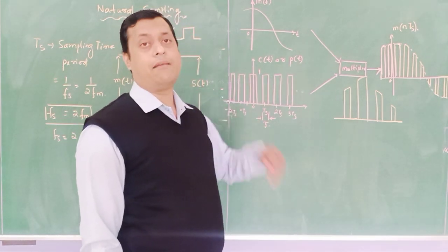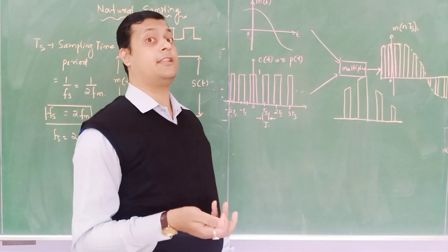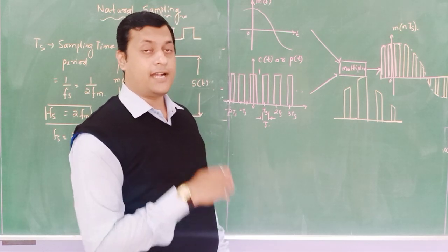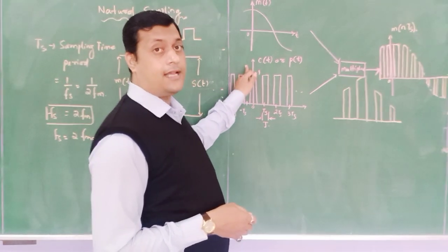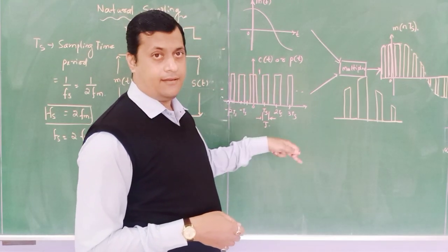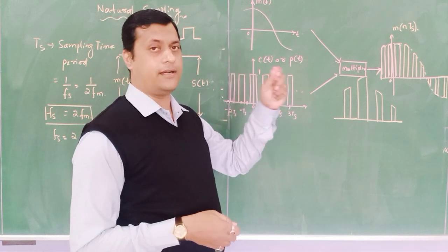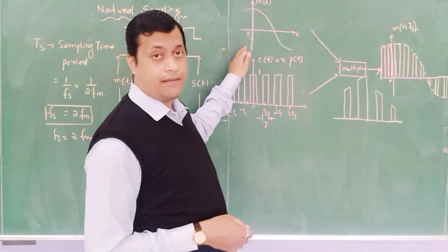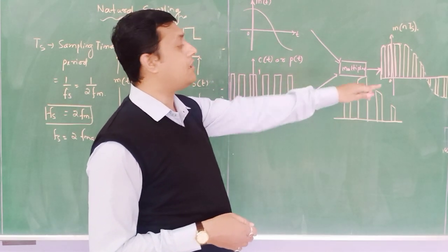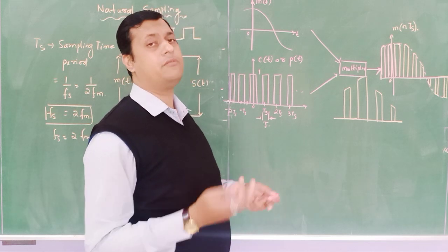But if natural sampling is followed by quantization, then we can get the discrete values. In instantaneous sampling, since we considered an impulse train, we directly get the discrete positions with discrete values. But in natural sampling, the number of samples we obtain is at a regular time interval of Ts, but the amplitude varies.